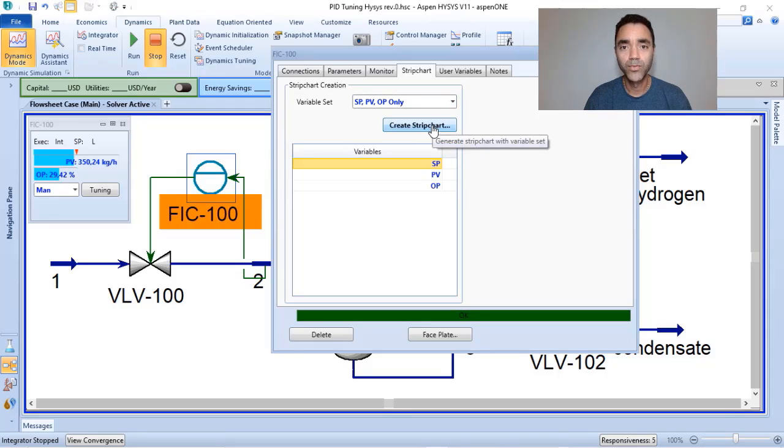It's very important when you are evaluating PID tuning that you observe not only the PV reaching the set point, but also the opening of the valve, because when you are doing a PID manual tuning, observing the behavior of the opening of the control valve, you get a feeling to know if you need to increase the KP, or if you need to increase or decrease the TI, and so on.